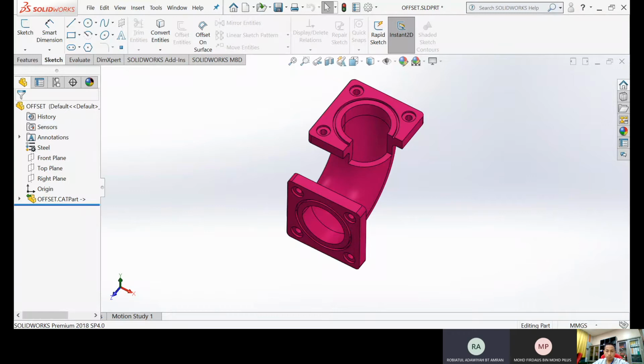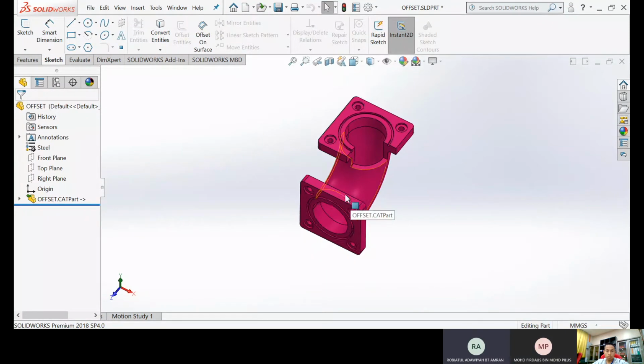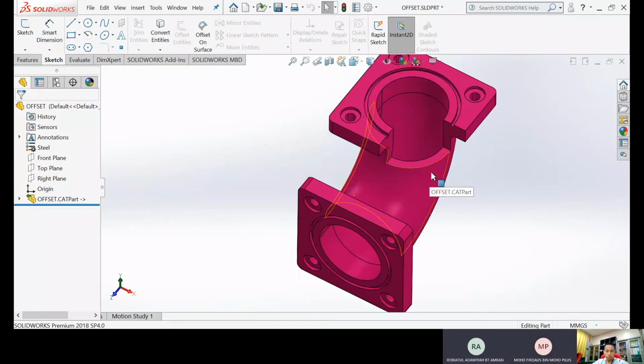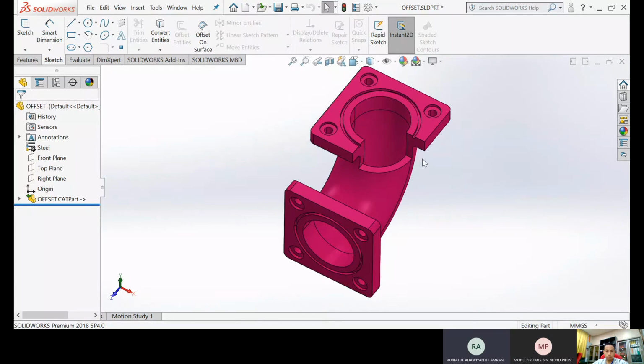First, turn on Scan 3D to save it as a file. Second, select the units that will be used in this design process. Third, to manipulate the feature, turn on 3D scan to get the tools needed, as this process deals with a third-party scanner, which has a PLY file that was saved out from its proprietary program. Fourth, STL section is used to trim, remove extra data which is not needed, and simplify the STL. STL edit is used to move, rotate, scale and locate the feature.